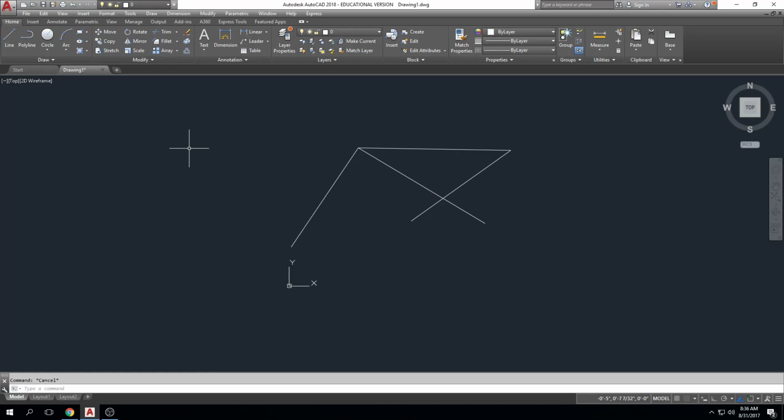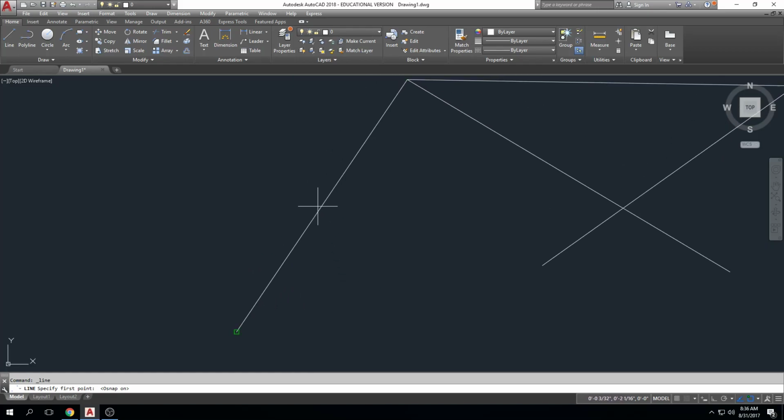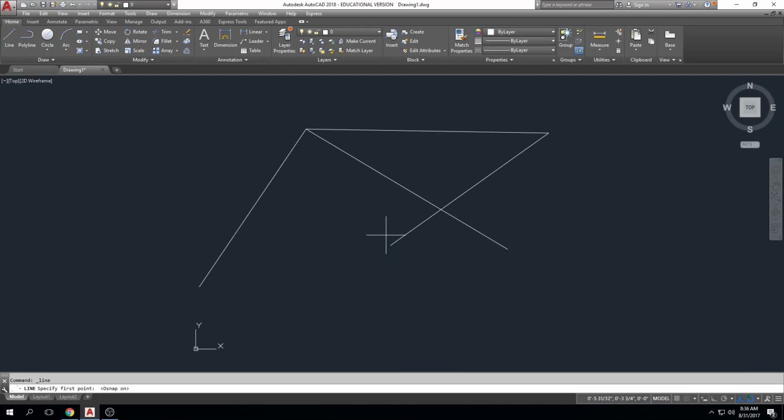And we're going to talk about a couple of other object snaps, right? I initiate my line command and I hover near, and you see I'm not clicking, I'm just hovering. Oop, my endpoint one is engaging, but that's not the one I want. Ooh, the one I want I don't think is turned on. All right, let's go turn on the one that I want, which is the midpoint snap. And while we're turning it on, I want to show you all of the other object snaps that we have available.